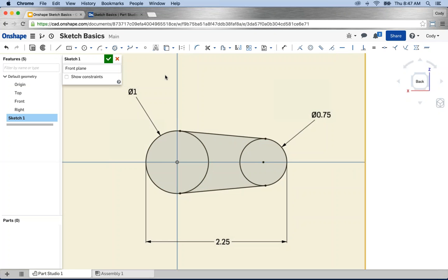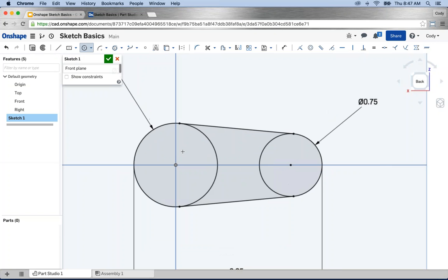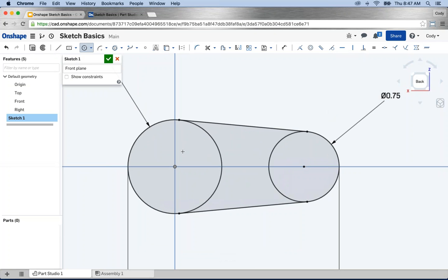All right, so one last thing I want to do, we're going to add 2 more circles. Now, I want to deliberately draw these circles off of their position. You wouldn't, and I realize that, but just for the educational purpose, I'm going to deliberately place these circles out here in random space. And of course, I want these circles centered inside of this circle. That's the goal with this, and there's a few ways you can accomplish this. What I'd like to show you is the concentric constraint.